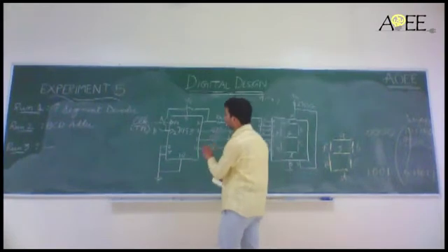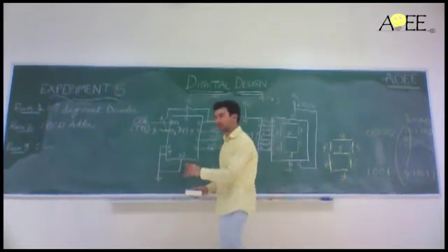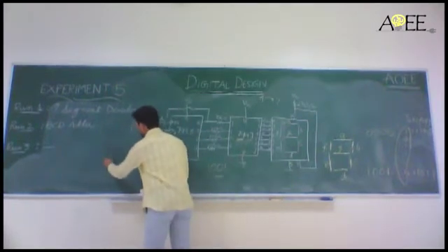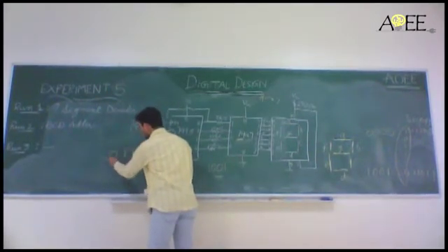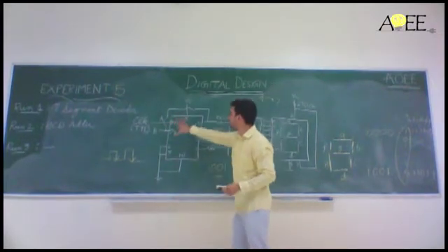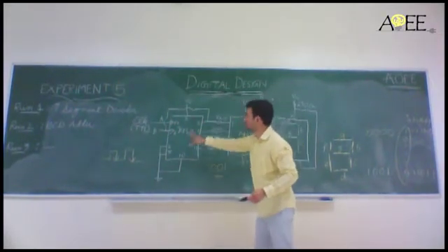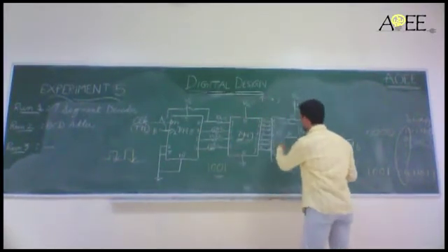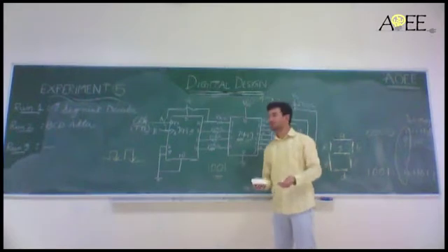So the main things involved in this are the connection of this circuit, giving A to the TTL logic. The TTL logic will generate these pulses. It is negative edge triggered because there is a bubble over there, and then when the 7493 counts, I mean the numbers are created, whatever is there, then correspondingly the FND will go accordingly.